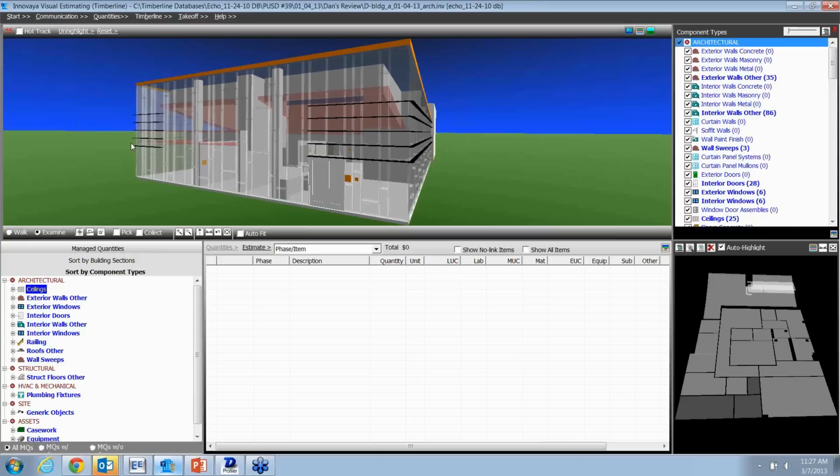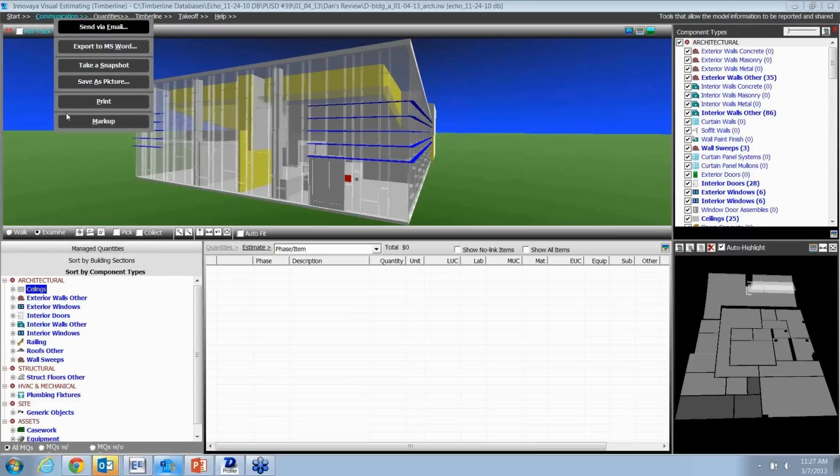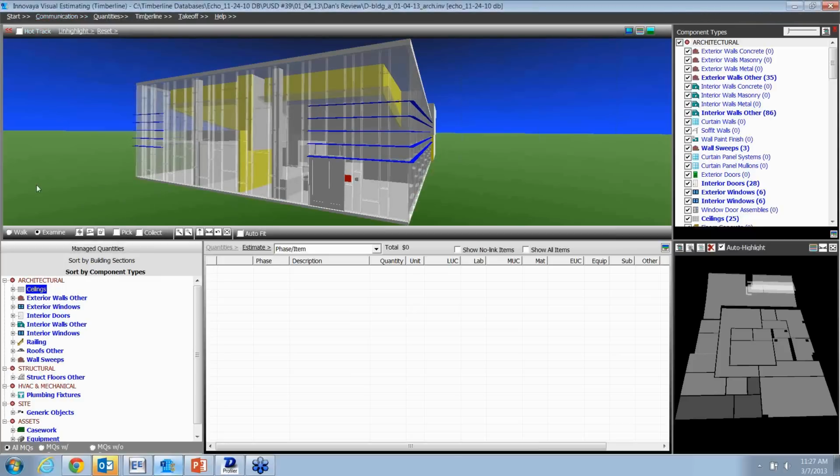The other thing that it does in a great way is that back in Revit, when we're working with that model, you can reference a previous set of drawings and do what they call show design change status. What that does is visually show you what's changed. Before, we would take pictures, send them out and say, this is what's going on, why did we do this? The way I've got the color coding, blue's been deleted, red's been added, yellow something's changed.